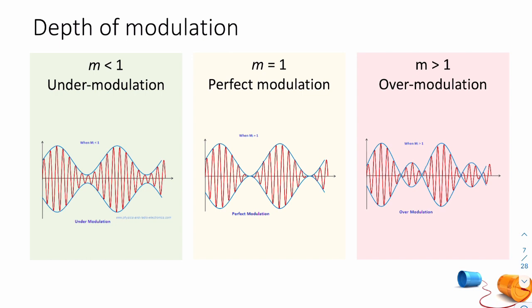Remember we spoke about the modulation index, and we said that it is generally less than 100%. When the modulation index is less than 100%, you have an envelope where the maximum and the minimum don't overlap, so there's always some carrier component. As we increase the modulation index to 100%, you have instances where the amplitude of the carrier is 0, because the peak and the trough of the envelope are touching but not overlapping.